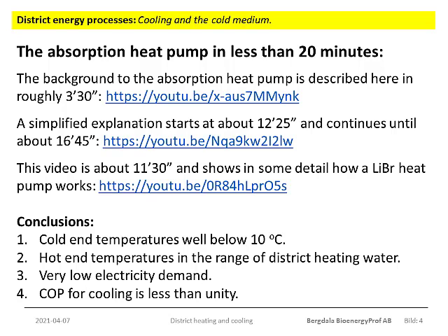The point with this combination is that the water is used as the refrigerant. Since you will most often want to co-produce and sell electricity, you do not want to have a very electricity demanding process in the plant. You want to sell the electricity, not use it internally in the processes. And the absorption heat pump demands very little electricity. The price paid for these advantages is that the COP is less than unity.